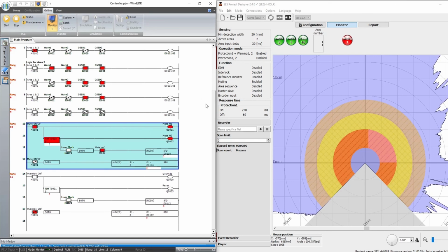So as you can see, the sequencing which I've done has already been done here. I'll bring the object. It's in the protection zone now, but the OSSD signal, that is the protection zone signal, is in a healthy state because we have bypassed this specific area. Let's say I'm moving the object to the protection zone now. So a small area has come to the protection zone. What happens now? Even in this case, it should bypass that area.